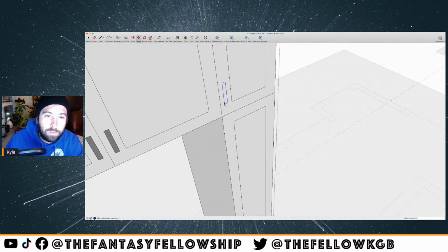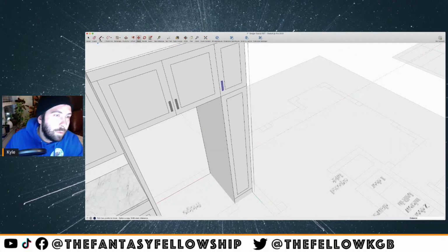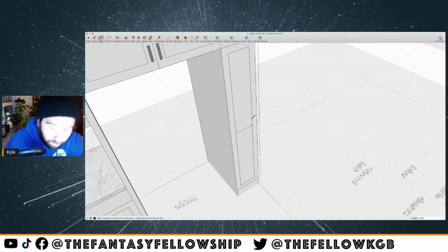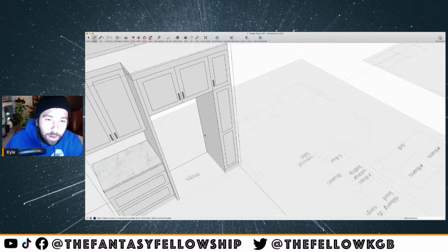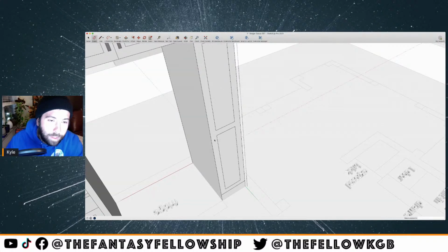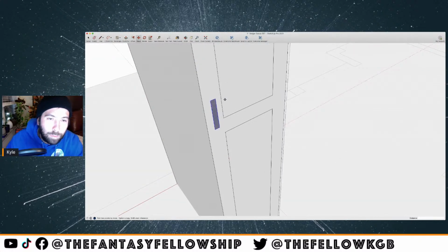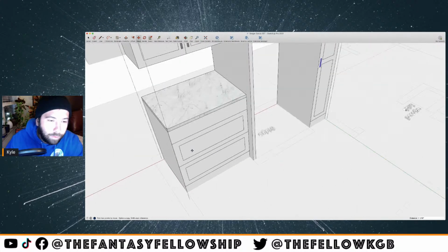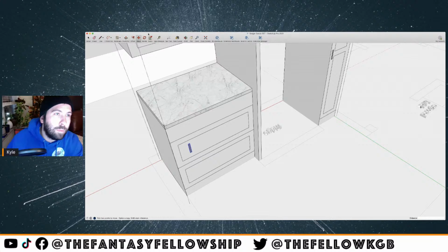And then before I get farther, I will say, typically when you get a really tall door like this, they're going to split it and put this little panel in the middle of it because it will add some structural integrity to the door. So I'm just offsetting, and I'm going to continue that 2.25 look there. That's typically how they will make a taller door like that. So it has a little bit of stability in it, and it doesn't bow or have a curve to it. I'm going to go ahead and put these handles at the drawers,